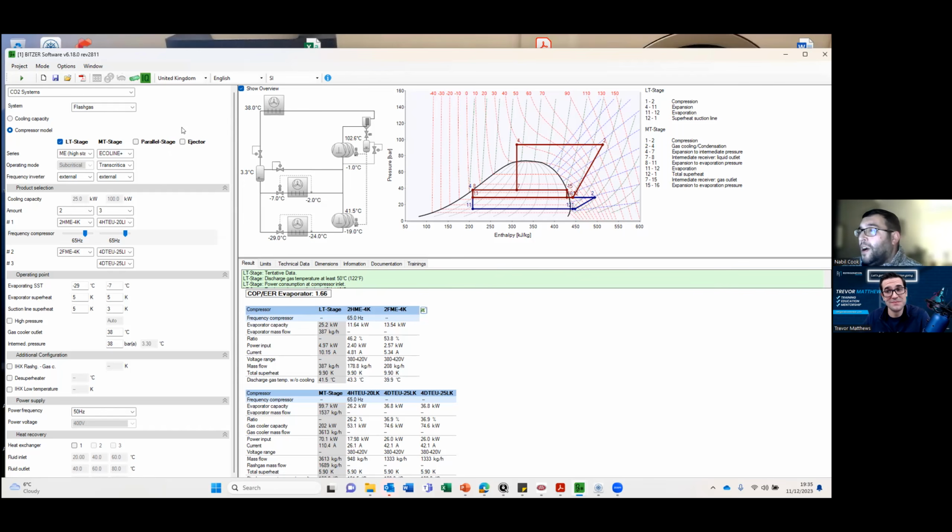Because when you are artificially elevating discharge pressures, or you're running a false load, or you're using a gas cooler bypass to make sure that you maximize your heat recovery, what are you going to have? More flash gas. And that keeps your parallel compressor running for much more of the year than what it would do if it was only being used in high external ambient temperature conditions for a few hours each summer per year.